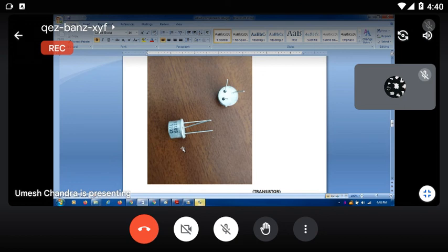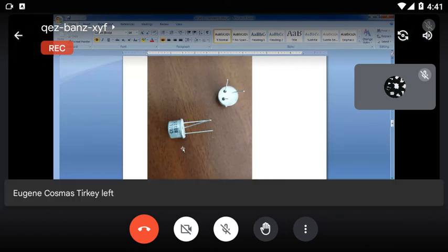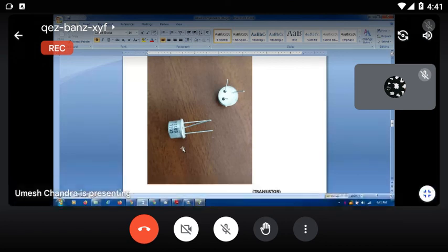Okay, sir. Remember means many numbers. And how do you know that number is NPN or PNP? Sir, what do these numbers signify? That BD125 CD, I tell you, B means silicon, D means some specification of the transistor. Some specification of transistor means starting from A. A means germanium type transistor, B means silicon type. Here starting from B, B means silicon type.